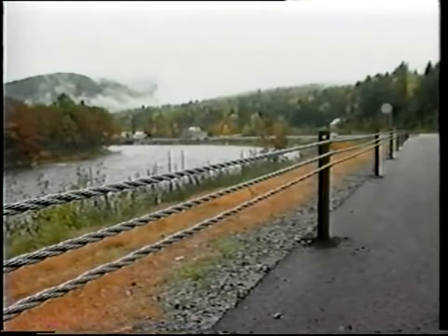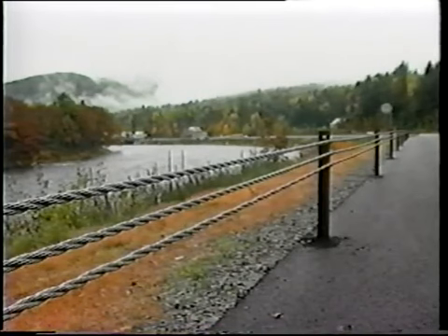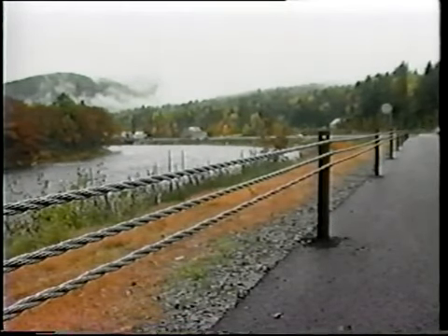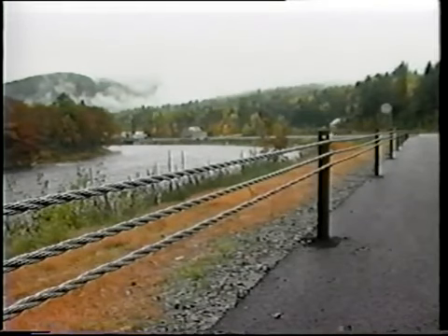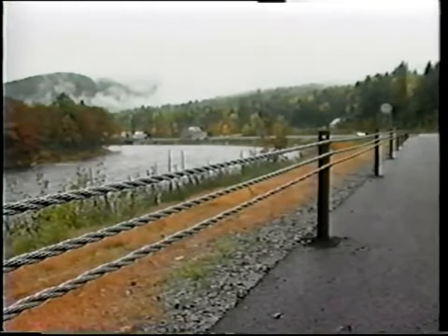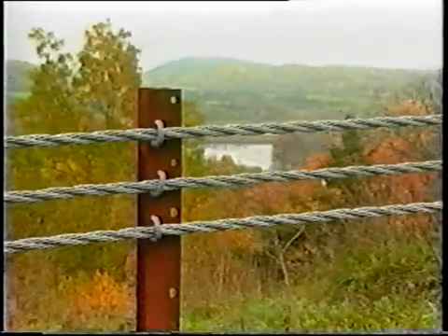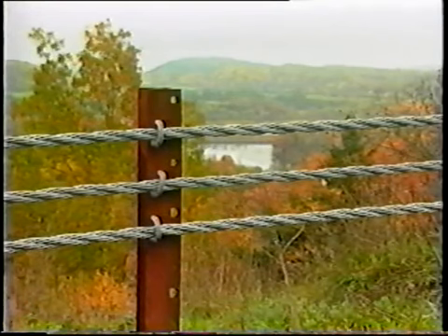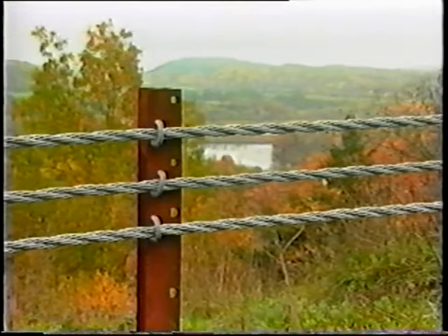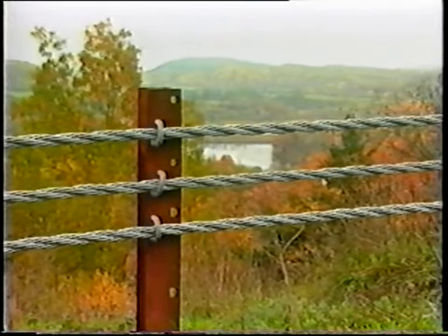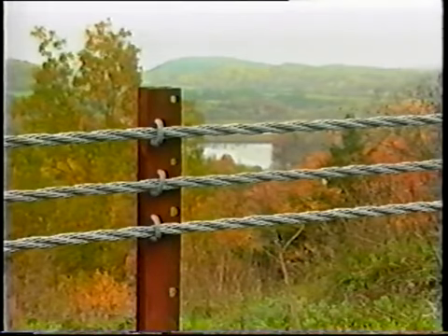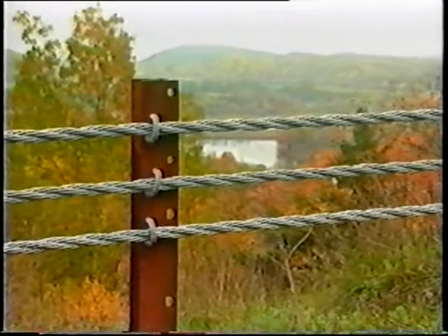While cable systems are often used on major highways, their reduced cost makes them particularly appropriate for low-volume, low-speed rural roadways. Even the inexpensive G1 guardrail shown here may not be cost-effective on some low-volume rural roadways. Several new, less costly variations of the cable system were developed in a recent NCHRP project for application on roadways that might not warrant more expensive systems.